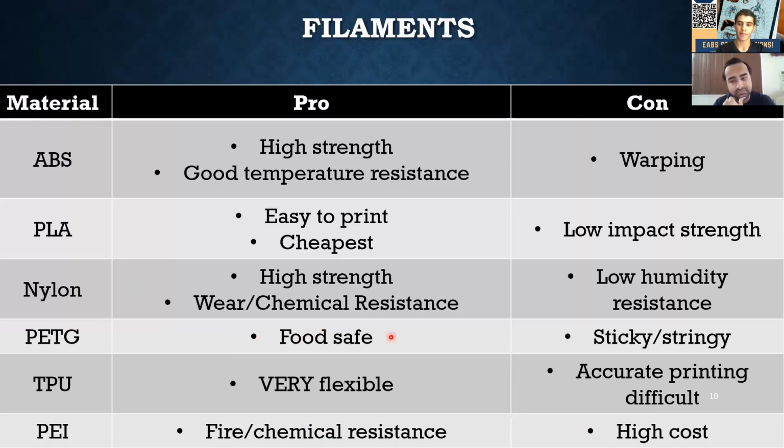Hmm, I think it relates to the application as well. Most accurate? Well, for application, it's whichever one works the best. So if you want something that has a give to it, use TPU. If you want something that is very structurally rigid, use ABS.